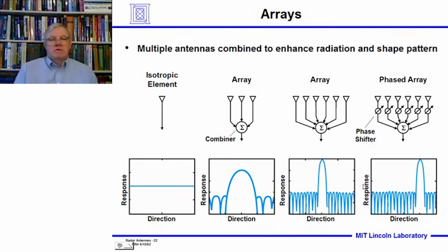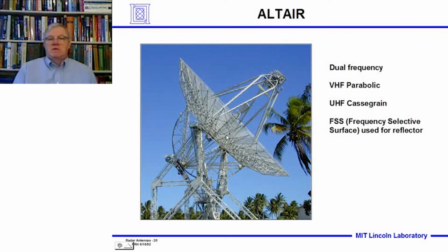Now, I'm going to steal my own thunder. People decades ago invented ferrite phase shifters that could shift phase at high power in microseconds. Imagine that big antenna that we just saw, I'll go back to it for a minute. Say it's pointing up in space in one direction. You wanted to move that antenna 30 degrees or 20 degrees over in space. Big motors. You can imagine the inertia in that antenna to do that.